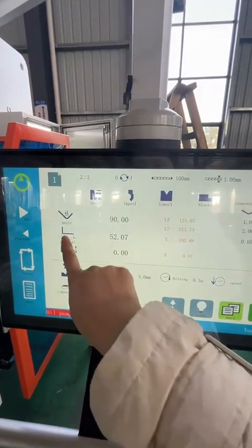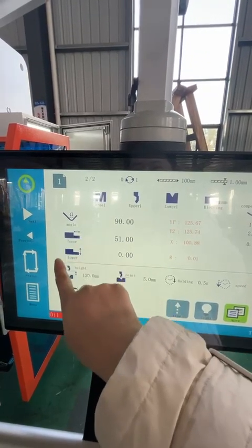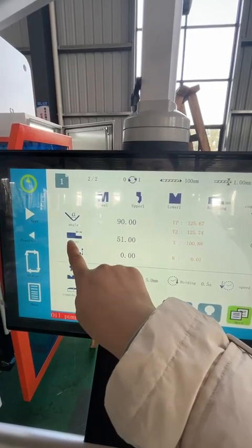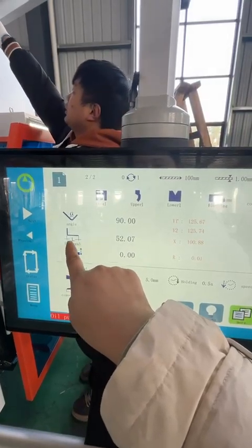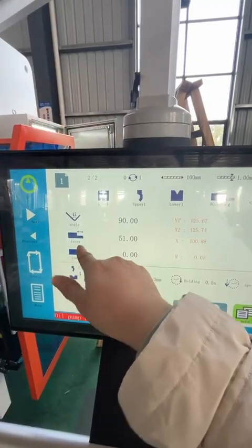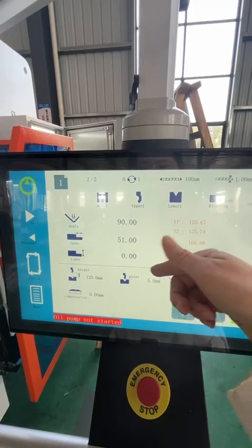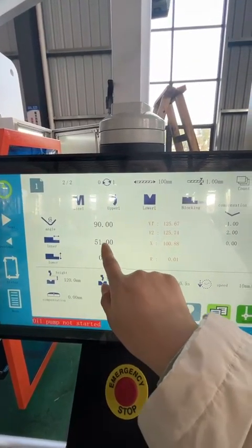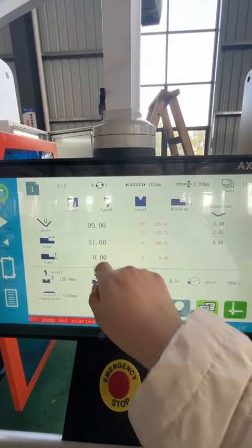And this is for the back gate distance. It has two measure ways, for the inner and external. So if you choose the inner, you have to measure the sheet from inside the distance. We have to reduce the thickness of the sheet. And this is the distance you can just enter here.